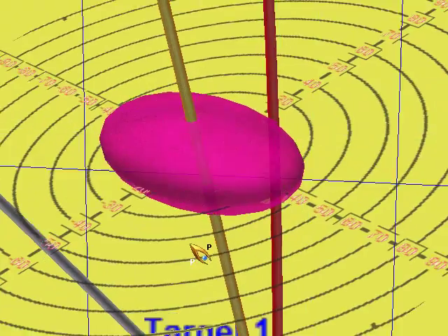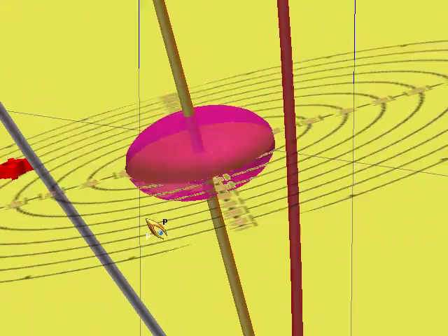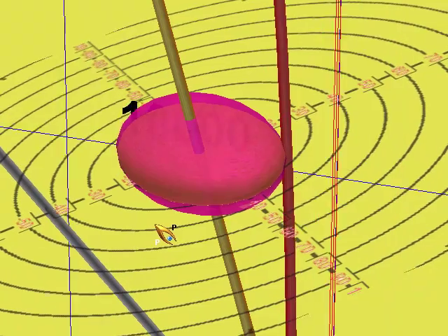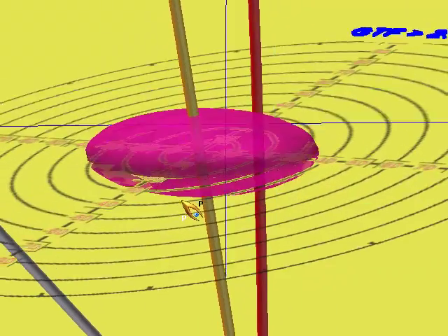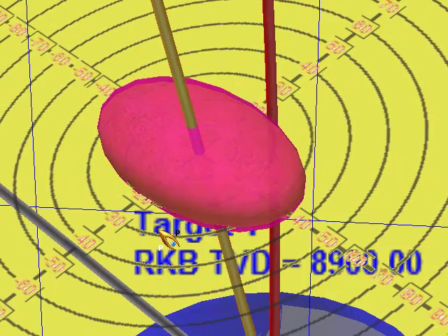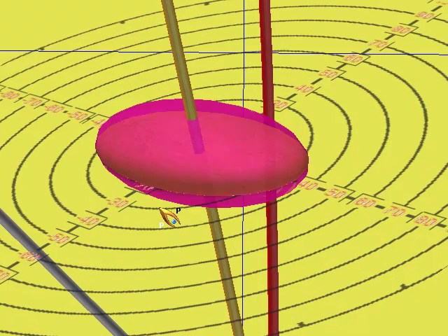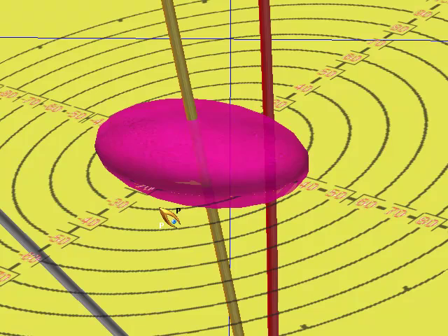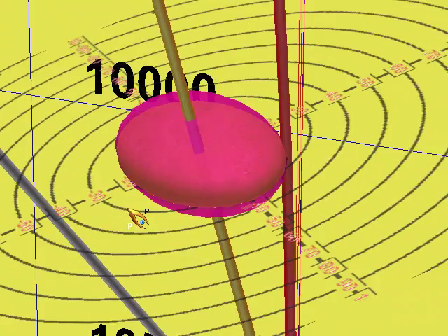All the parameters and weighting functions used for those tools are incorporated in the determination of that covariance matrix, and it's from there that we get the dimensions. Once we get those dimensions, it depends on whether we're working with 1 sigma, 2 sigma, or 2.5 sigma. 2.5 sigma in this instance will give us a 95% confidence level.